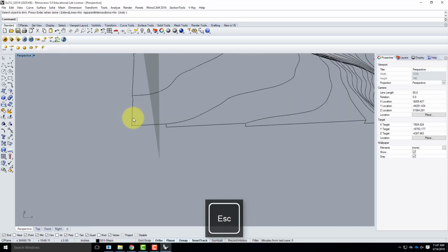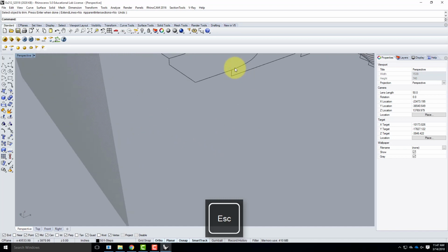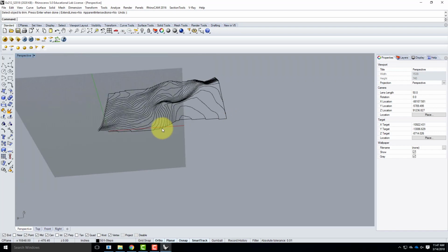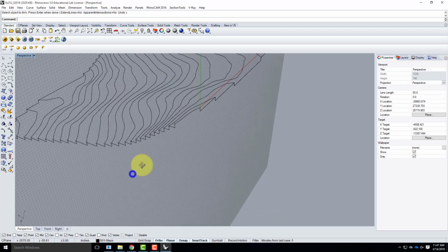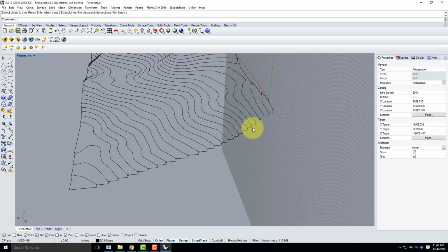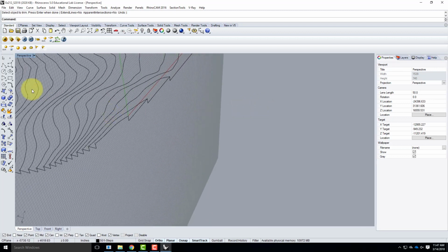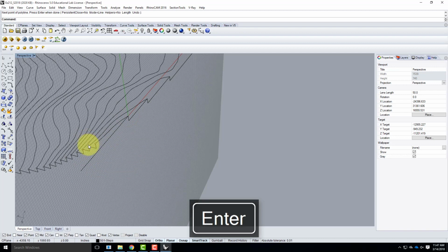And what do you do about that little guy? So that corner, this goes up and to the corner and then back and then up to the next step. So the corner should be level, unless your contour meets exactly in the corner. But not everybody's is going to do that. So let me come back to this corner. I've got another problem here. This one is like at the top of the hill, like the example that was at the top of the hill. So this one's going to go from this step there, straight out. And it's going to go from that point there, straight out.